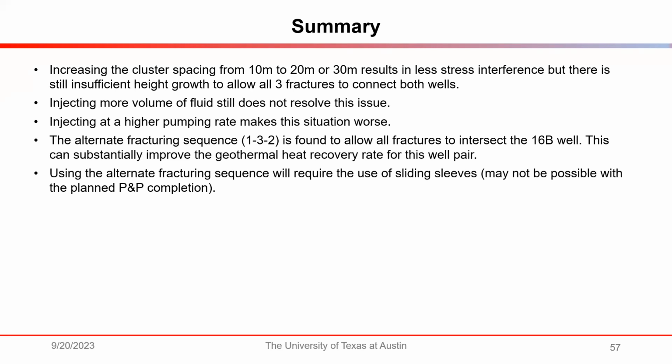Yeah, so I've done some similar kind of modeling. Last January at the Stanford Geothermal Workshop, I had a paper where I matched stage 3 with a planar frac model. I had to vary some things like the fracture conductivity during propagation, and got a really nice match of the geometry. More recently, we've taken some standard out-of-the-box frac designs, 8 clusters per stage, pumped a normal slickwater frac job in them.